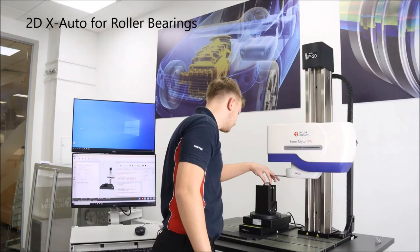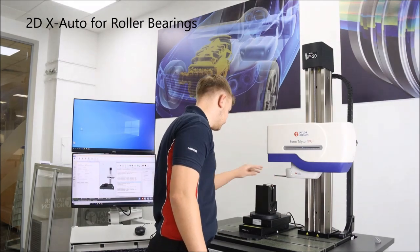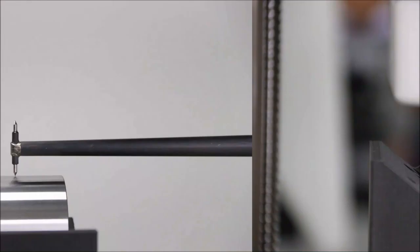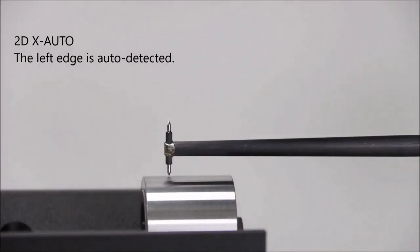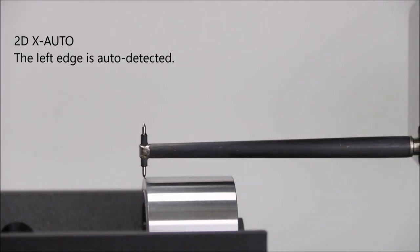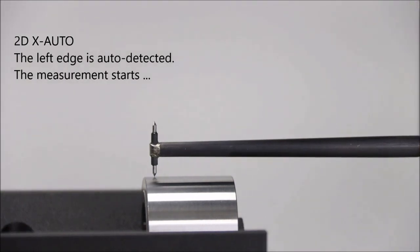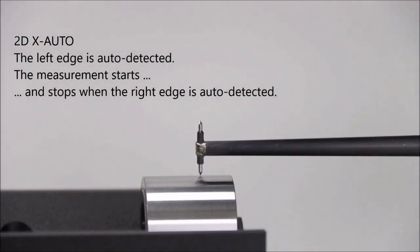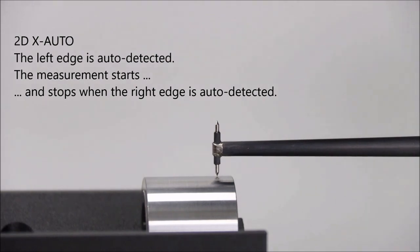We're going to take a look at the measurement of a roller bearing, where we're also interested in various dimensions and diameters. My colleagues put the bearing in place, started the measurement, and we've made contact with the surface. We're measuring the upper external surface at the moment. We're automatically detecting the beginning and the end of the measurement. The stylus tips there are 2 micron conisphere diamond tips.